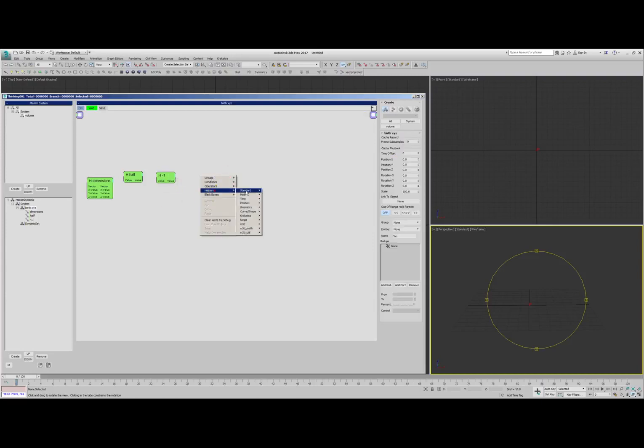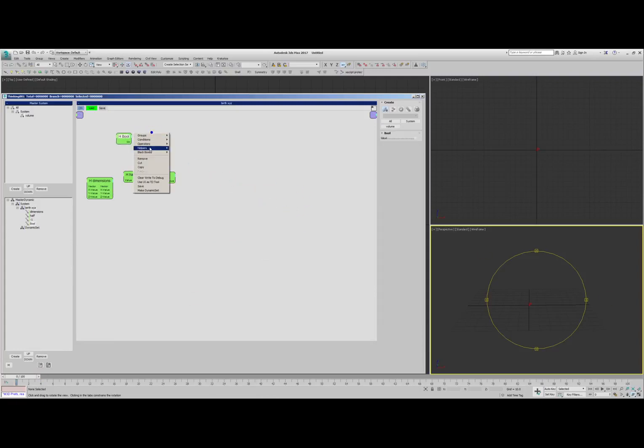And one of the things we definitely need is we only want this to happen at this first frame of the sim, at least for this particular case. So we're going to use a Boolean connected to an egg timer, which is the easy way to do this. And easy is nice. Let's have it only fire once, so we set that to single. For 0 frames, you don't need a number of frames, it'll still process. And what will happen is we're just going to use the reached value coming out of there.